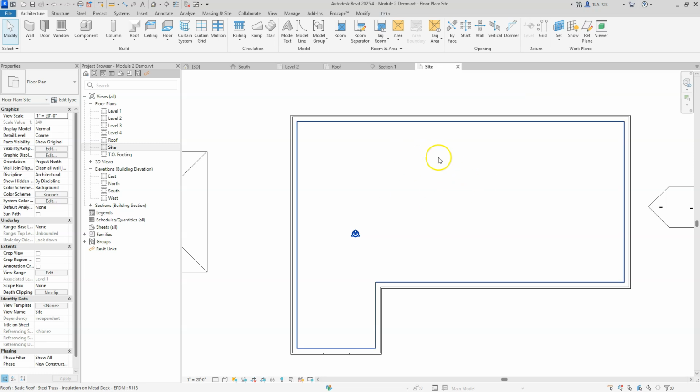On a commercial roof like this, what we're actually going to be trying to do in a lot of cases is push that water to the inside of the building to an internal drain that is going to go down through the building and ultimately to a storm sewer outside. Or it might even just poke through a wall outside to a splash block of some kind to push it away from the foundation. Either way, we're actually going to route that water from the roof through the building. Sounds dangerous, but it works really well as long as you install it properly.